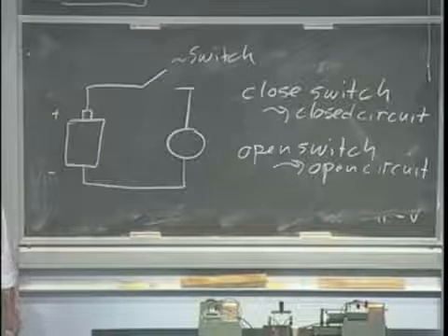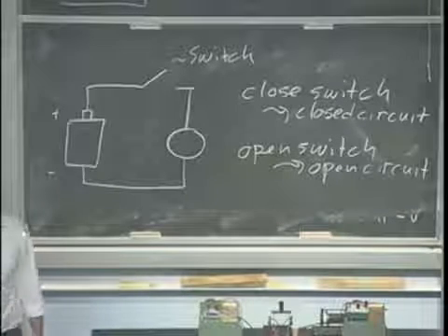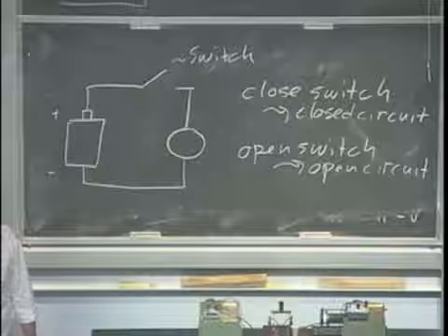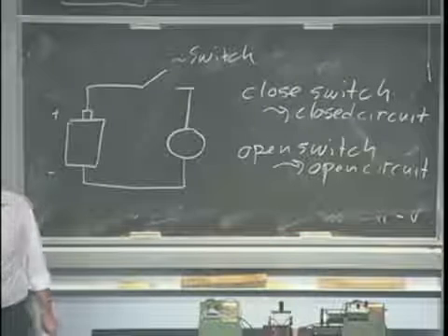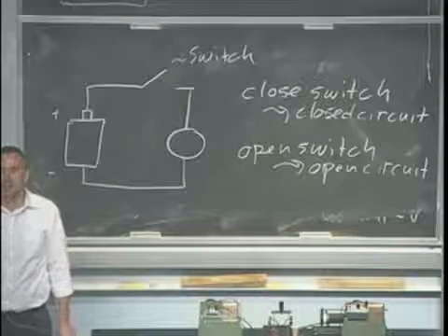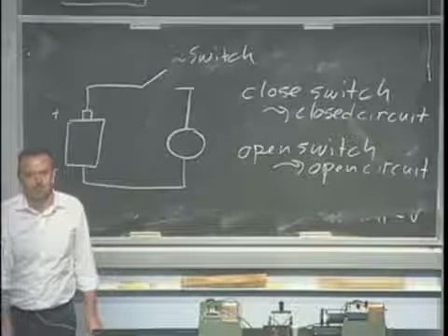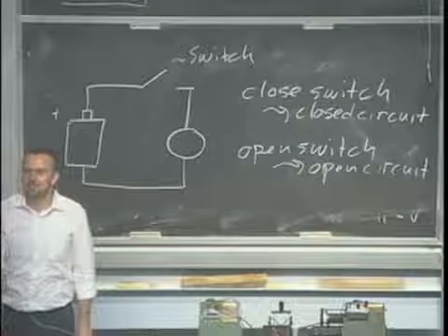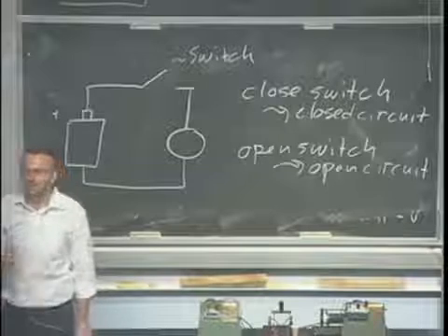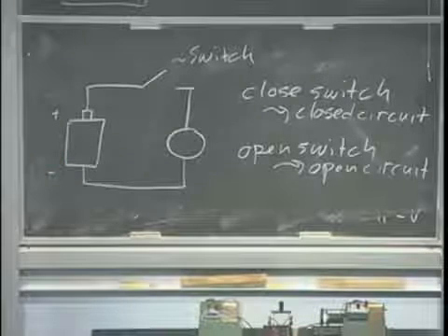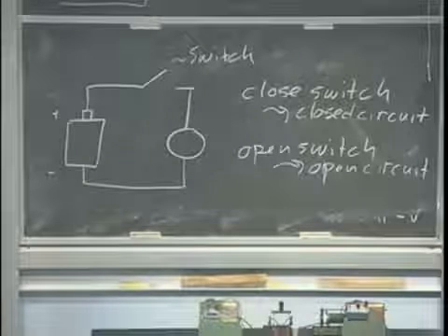That's also why when people are working around voltages or high voltage sources or some sort of current sources, they usually wear rubber-soled shoes. Okay? That's because those are very poor conductors, which means that if you touch something that's a high voltage by accident, then current is not free to flow through you because it has nowhere to go through your feet. Okay? Whereas if you're barefoot and touching the ground, or if there's water around, good conductors, then current can flow. Okay, so with rubber shoes, you're a good open circuit. Okay, so that is our circuit.